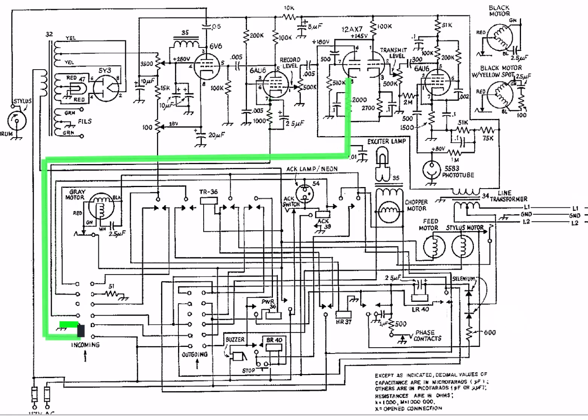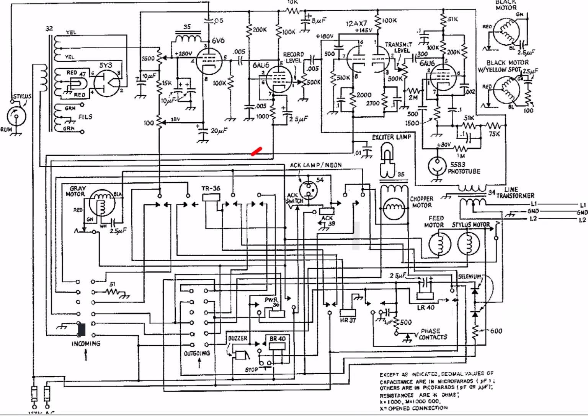That means that by default, the unit is in transmitting mode unless the receiving button is physically selected, and the receiving amplifier is enabled when this incoming button is then pressed. That selection happens no matter what else is going on with the circuit. It's just controlled by this one button.